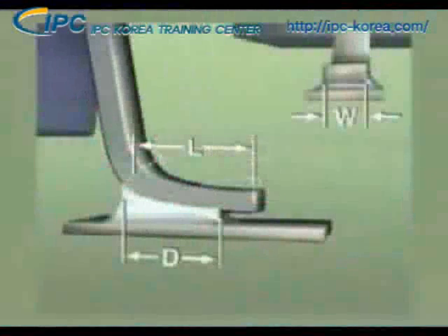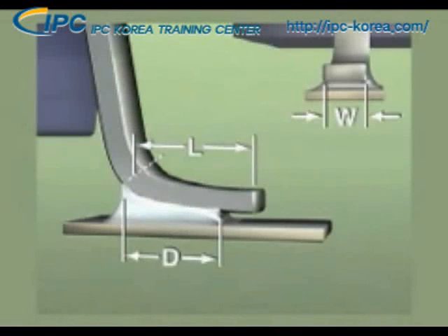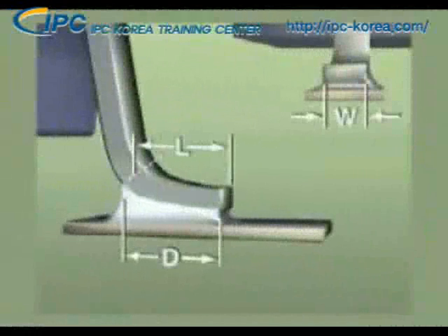If there is a long foot length, meaning that L is equal to or greater than 3 lead widths, the side joint length should be a minimum of 3 widths, or 75% of the foot length, whichever is longer. If there is a short foot length, meaning that L is less than 3 lead widths, the minimum side joint length is 100% of the foot length.